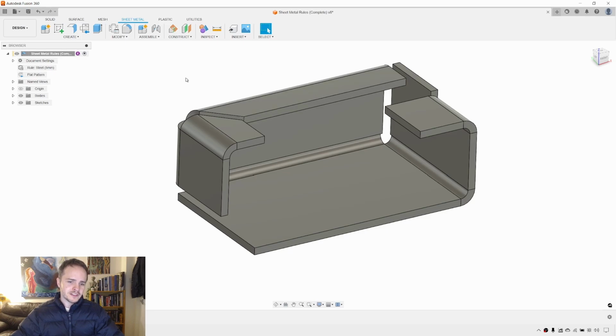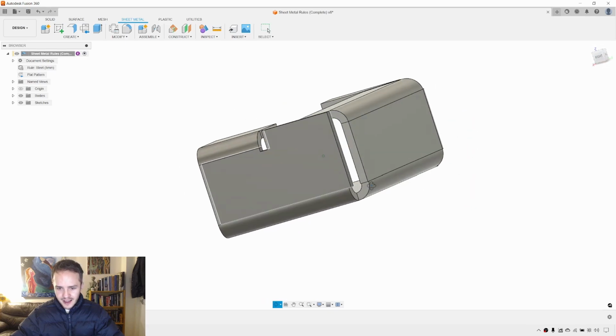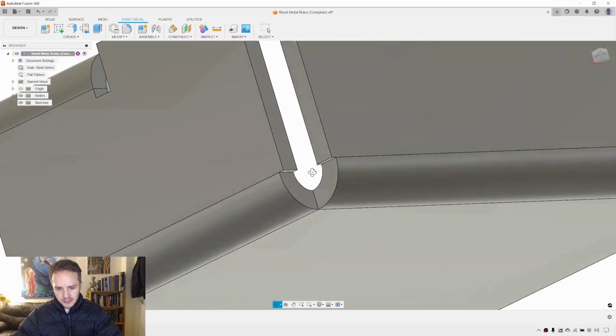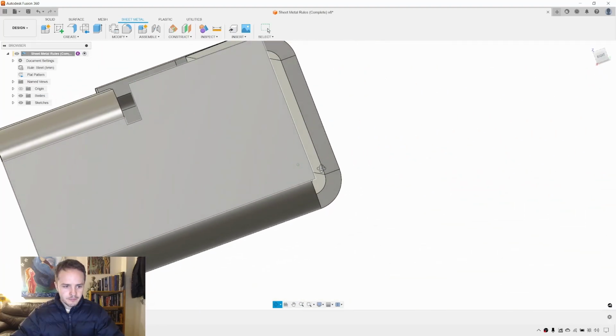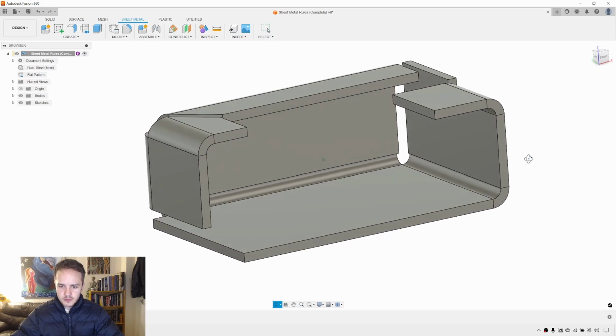But we can see that the sheet metal rule that governs this design is the 5mm steel sheet metal rule. So here we can see that the thickness of the sheet is 5mm, and it's got a particular way of dealing with corner treatments and bend reliefs and bend radii that can all be changed with the rule.